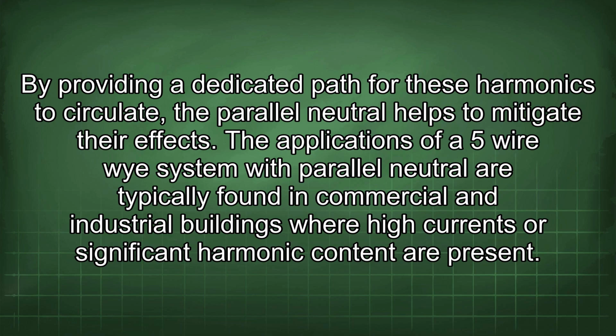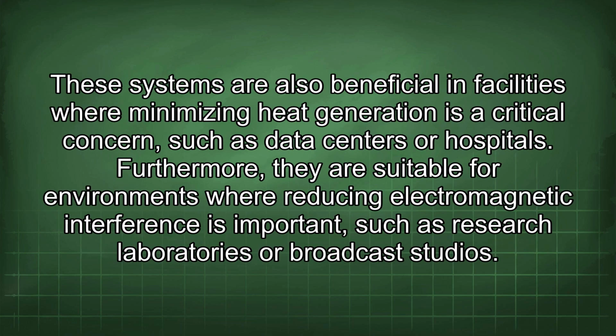The applications of a 5-wire Y system with parallel neutral are typically found in commercial and industrial buildings where high currents or significant harmonic content are present. These systems are also beneficial in facilities where minimizing heat generation is a critical concern, such as data centers or hospitals. Furthermore, they are suitable for environments where reducing electromagnetic interference is important, such as research laboratories or broadcast studios.